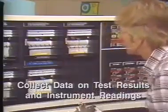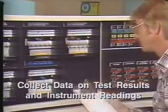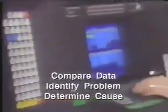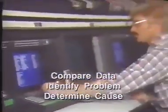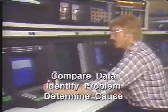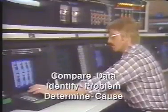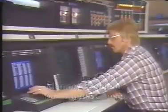The first thing an operator does is collect all data on current test results and instrument readings. Next, the operator compares current test results and instrument readings with previous data so he can correctly identify the problem. For any given problem, such as flooding, there may be several different causes. So in addition to identifying the problem, an operator must also determine what is causing it.